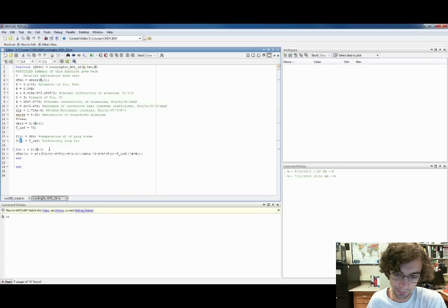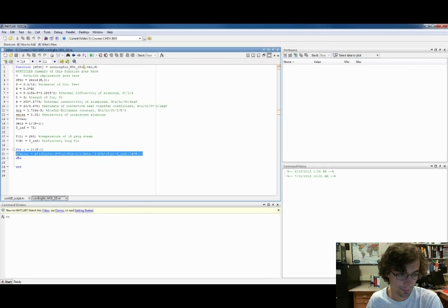Then the final, the temperature at the n node, so that's why I give it the index n, is equal to the ambient temperature. So that's the infinitely long fin case, the assumption that I talked about. Okay, and we'll need to repeat these boundary conditions in our script file, which I'll show you in a bit, so that MATLAB can keep track of boundary conditions and can basically pin down these temperatures at these points and solve the solution accordingly.